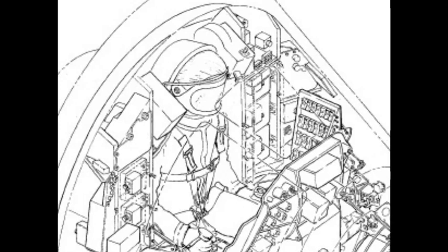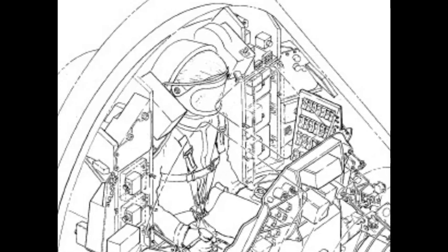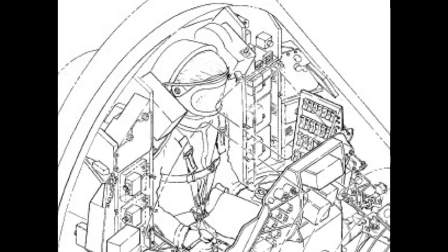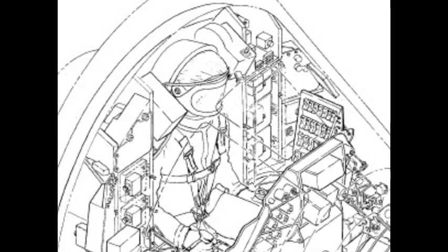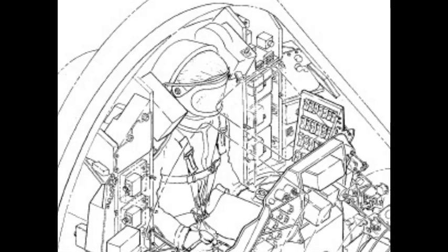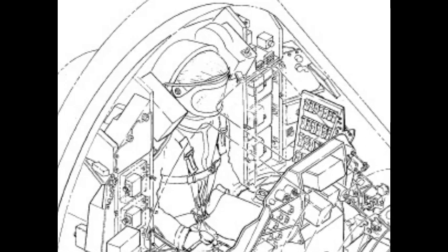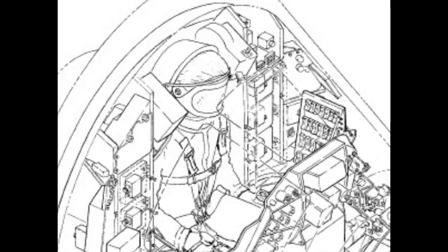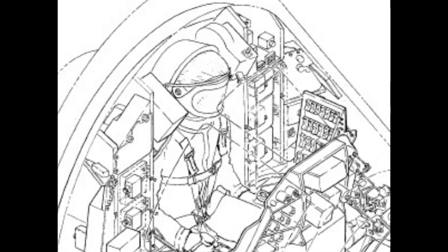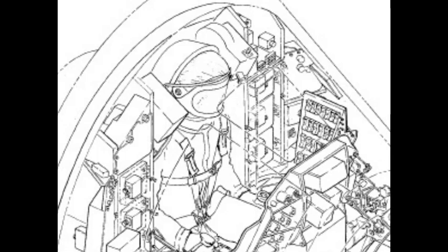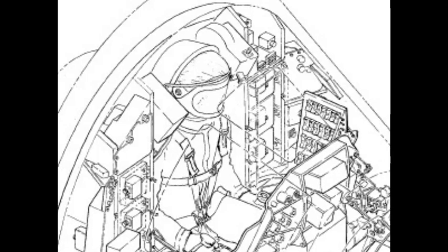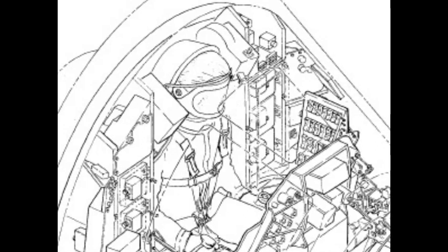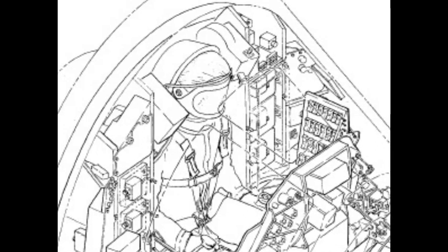Electrical wiring is routed through the structural tubing, from the rockets to connectors located on the pylon attach ring. Prior to capsule launch, the pylon is installed onto the capsule by clamping the pylon attach ring to the capsule recovery system compartment with a chevron-shaped segmented clamp ring. Explosive bolts connect the clamp ring segments in tension.